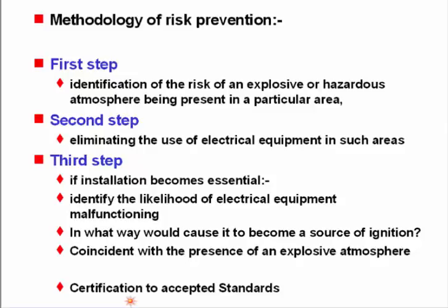Here in Australia, we do not accept ATEX. ATEX is a mandatory requirement in Europe, so they have to have ATEX certification. Here in Australia, we only accept IEC Ex certificates, Aus Ex certificates, and ANZ Ex certificates. We don't accept ATEX because ATEX is a European trading directive and Australia isn't part of Europe. Likewise, in America, they are likely just to be able to accept UL listed equipment or FM listed equipment.